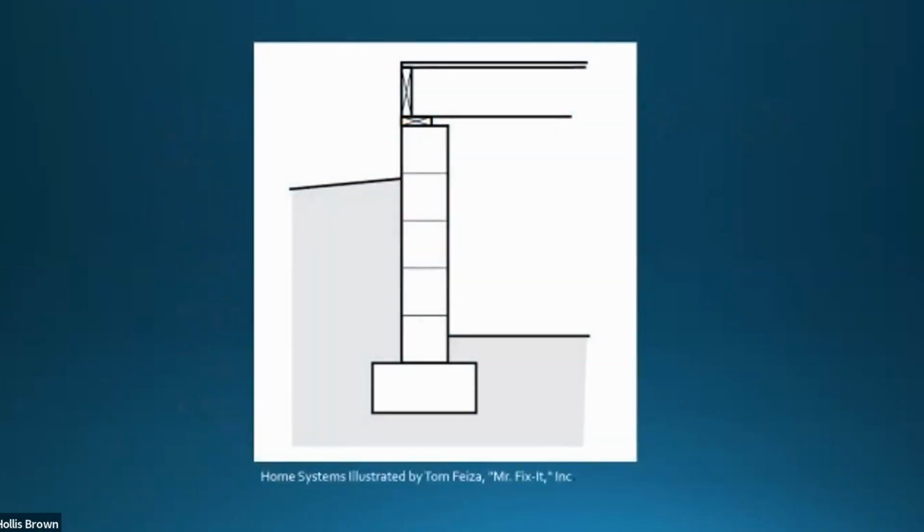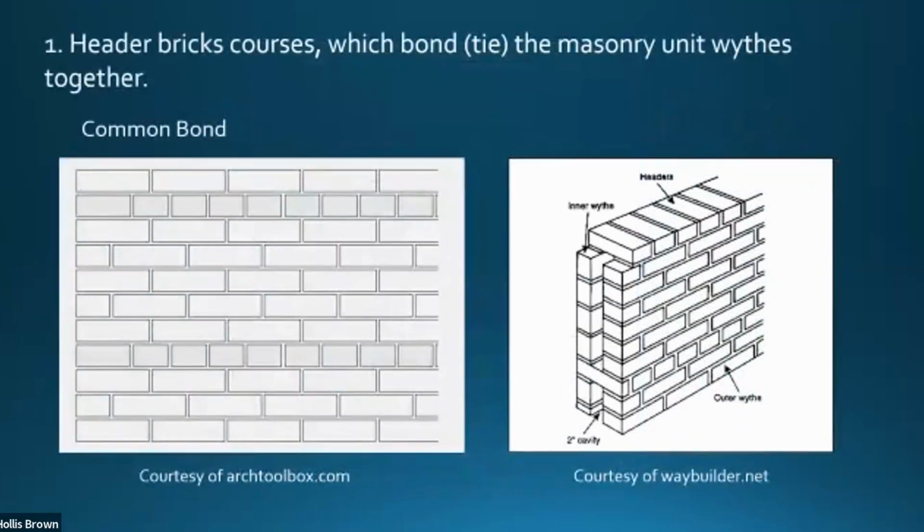And moving on to foundation walls. Foundation walls don't have to have that same level of thought in how they're built as retaining walls, because they have a floor system in a house to help keep them from pushing over. But there are limits to that. But before I go quite there, I'm going to touch for just a moment on solid masonry foundations.